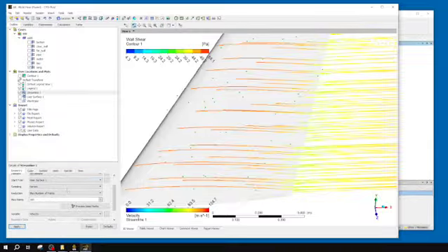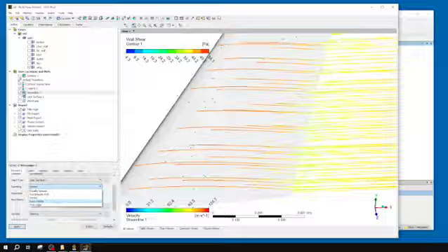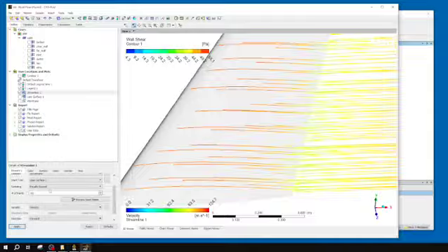This vertex method and face-centered method is going to bias places with more cells. So let's say you did extra refinement on the leading edge. If I were to do this vertex placement, it would put more points on my leading edge. Same with face-centered and free edge. So all three of these kind of bias it towards highly dense cell places, and those cells are defined in your mesh. But I found equally spaced to be the best working.